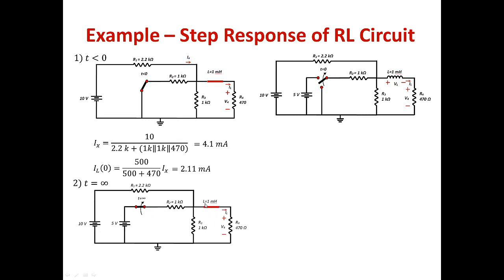Now we need to solve for IL, and this is a new circuit, so we need to analyze the circuit using a new technique. Looking at the circuit, I have 2 voltage sources, and I only have one unknown node, which is this node. It's better than the 3 meshes that I have. So I will use nodal analysis here. I will define this node over here and call it Vx. This is my Vx, and now I'm going to write the nodal equation for Vx.